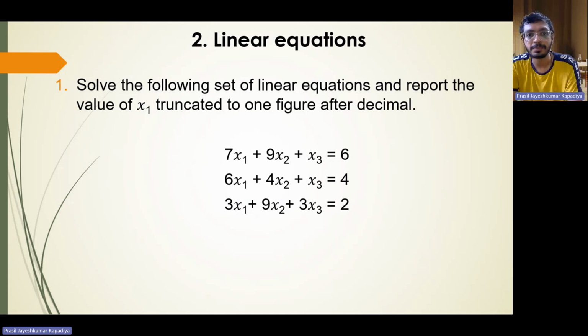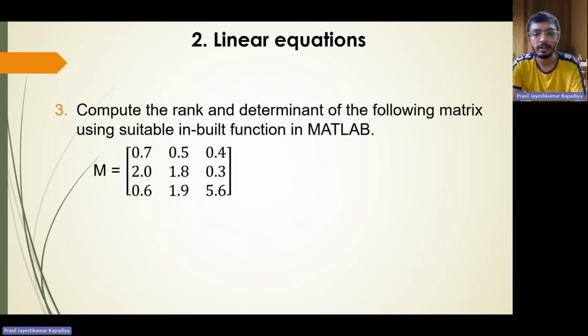For that, we used the fsolve command, the fzero command, and for polynomial equations, we can further use the roots command. And for linear equations, what did we learn? We learned the linsolve command, inverse of A times B if the inverse is defined, and A backslash B. Those two are the same. So this is what we learned, or revised, till now.